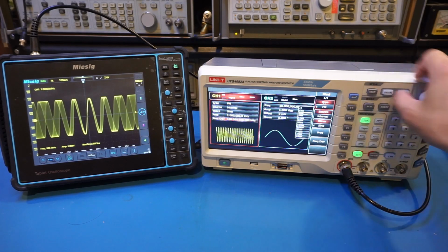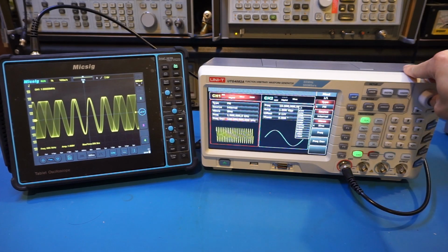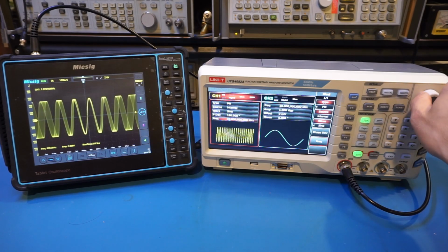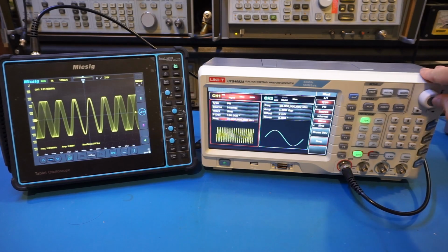So here, let's see, we have the phase modulation, and you will see very similar waveforms compared to the frequency modulation. Let's go down and change the frequency to 100. You can see that we can already see the phase shifts from the display here. And obviously the phase and the frequency are related. In this case, the resulting waveforms look fairly similar, but the mechanisms are slightly different.